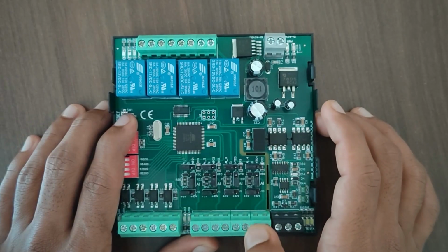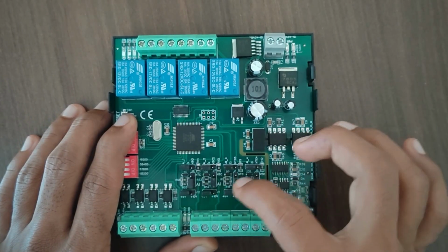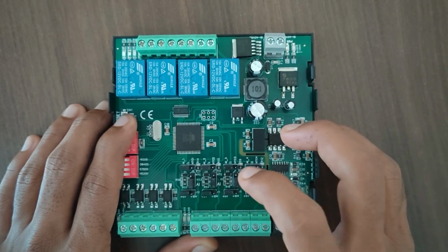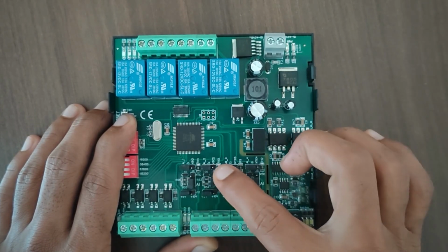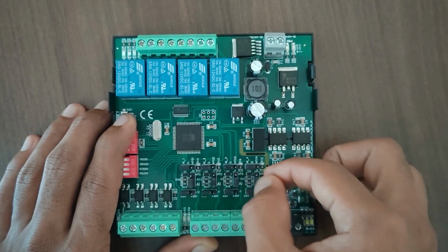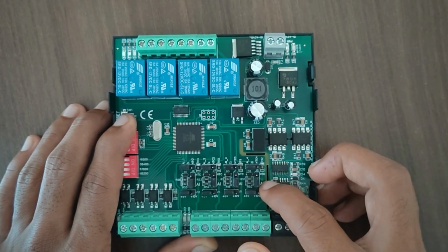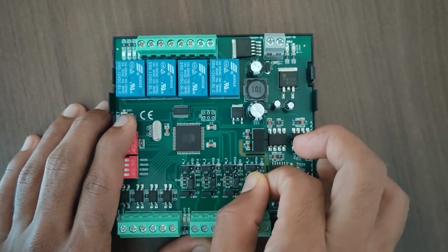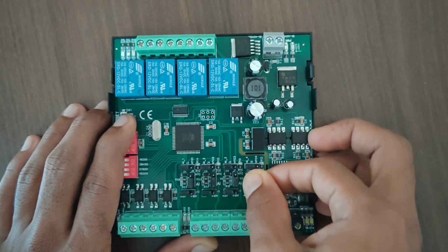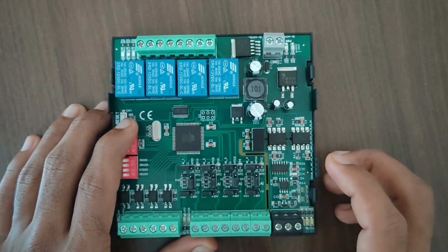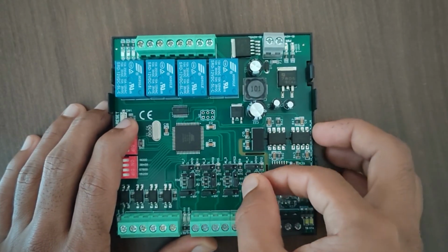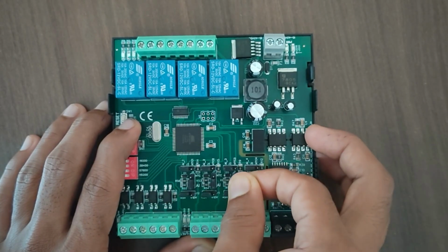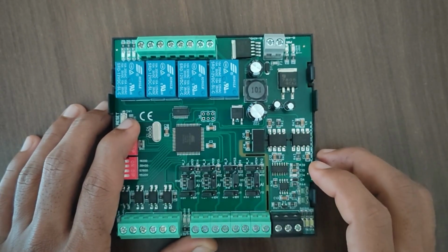And in this 4 AI channel, here we have the configuration for the switches. Whenever the user needs to set the AI part, at that time all jumpers need to be set in the AI condition. Here on the board they have mentioned AI and NTC. During the AI part, just set all the jumpers to the AI part. Whenever you need to shift to the NTC part, at that time just shift all the jumpers to the NTC part. Like this, simply shift the jumpers to the NTC part.